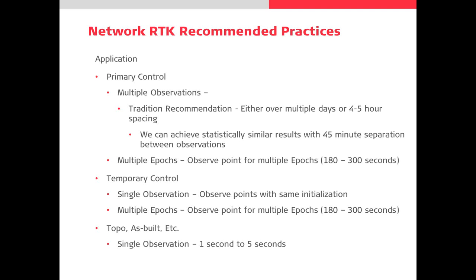Question is, when you're setting control, do you recommend using static initializations? That's for a Leica receiver. A lot of people don't have the option. Sure, you can use that. That wasn't part of the test that we're referring to here. We've seen good results out of static initializations. That's going to be a matter of personal preference and a matter of what you do out in the field.